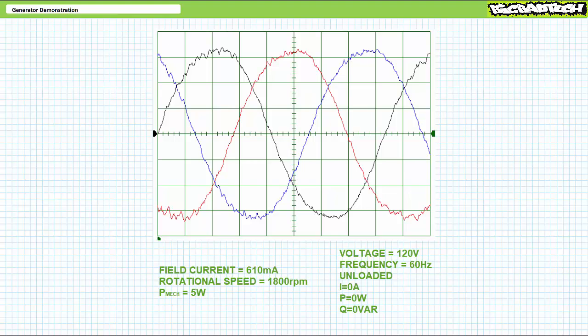Now, before we bring this lecture to a close, keep in mind this experiment made use of an isolated synchronous generator, i.e. one not synchronized to a larger grid. An analogy might be the one generator on some island or other remote location with no other power generation facilities. Understandably, there is a one-to-one exchange between the one generator and everything powered by that one generator.